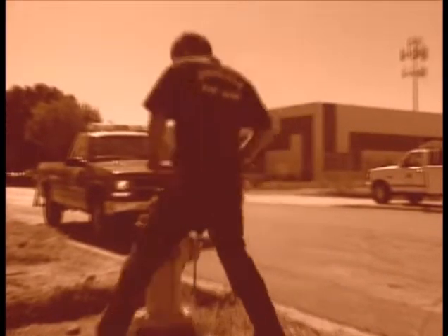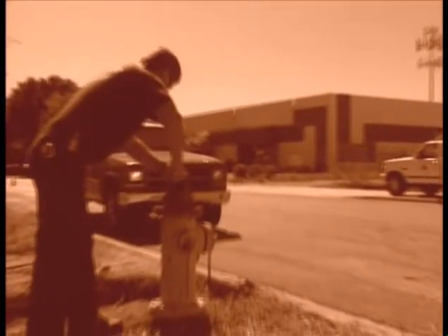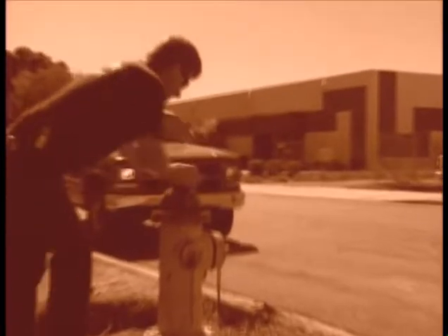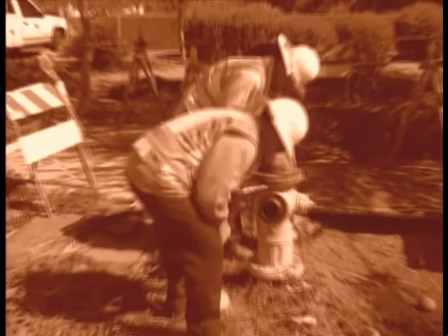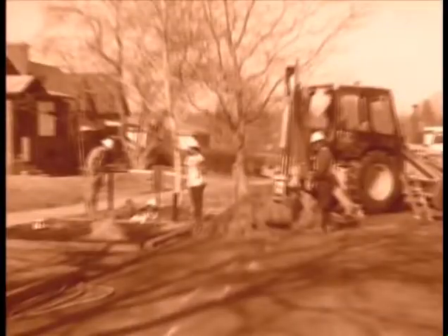A concerned citizen called the fire department when he saw what he thought was a leaking hydrant. A firefighter came to the scene and didn't notice the water department work crew just around the corner as he closed the hydrant. A quick buildup of pressure in the line blew off the fittings on the repaired main. 3 workers in the ditch were injured, 2 severely, when water and pipe materials struck them. During an internal investigation, the water department discovered that although out-of-service tags were used on hydrants that were broken and in need of repair, they were not always using tags while crews worked on distribution lines.